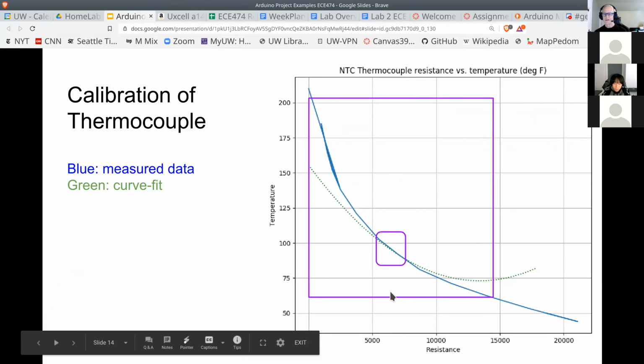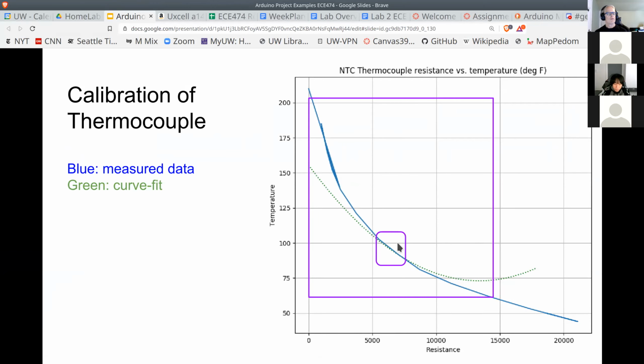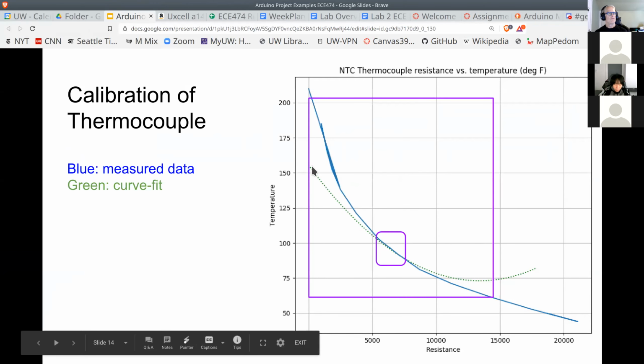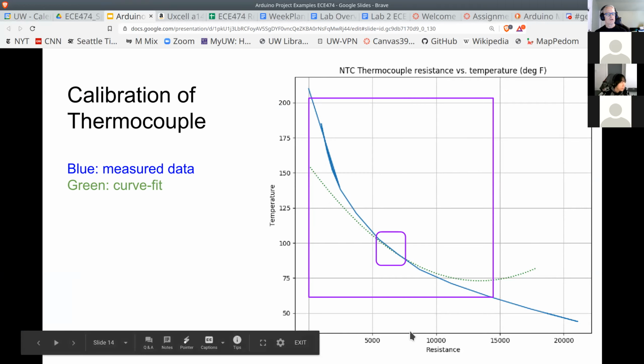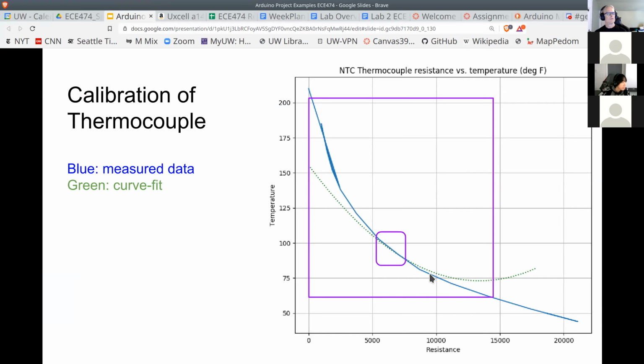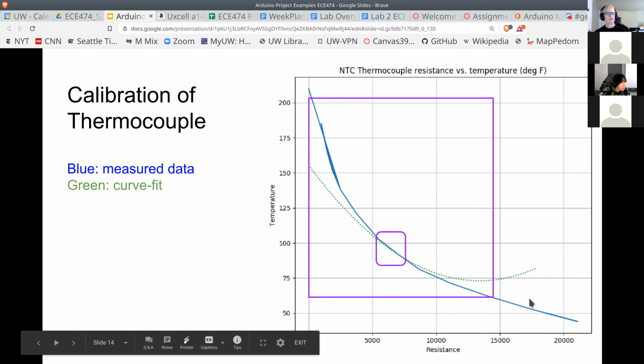Okay, where was I? Yeah, so this is the fermentation range, and I fit a polynomial, which was surprisingly difficult actually to this data, but I optimized it to fit in the fermentation range. I wound up not using the polynomial, but instead just interpolating between my data points. So I measure some resistance, go up to this line, and interpolate between these 2 points to hit the line, which is more accurate.